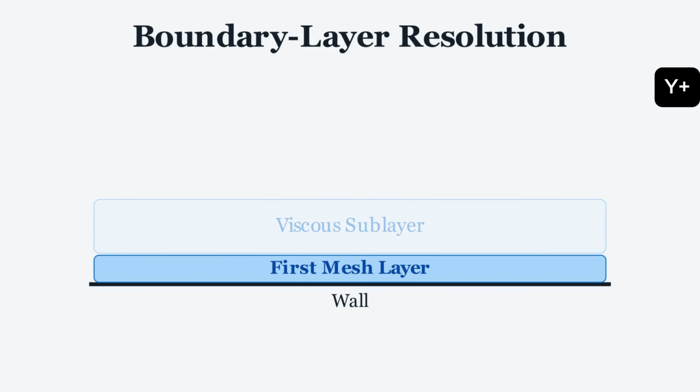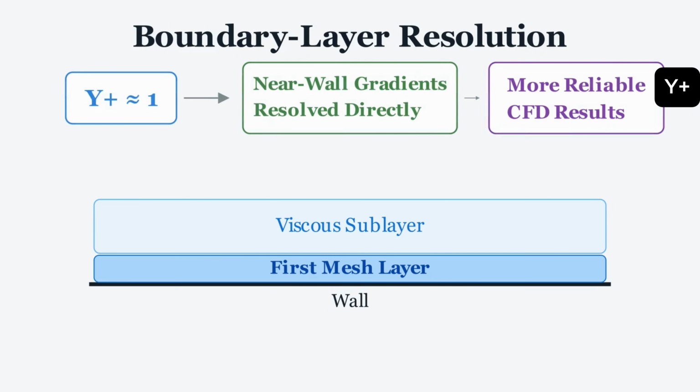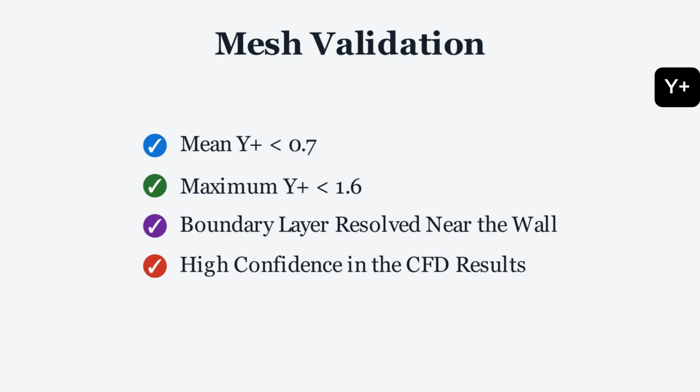Simultaneously, the maximum y+ value is controlled within 1.6, fully meeting the grid requirements for low y+ SST models, ensuring high confidence in the simulation data for boundary layer flow capture.